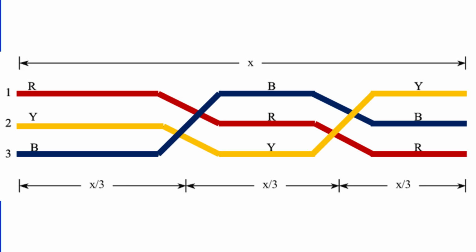Another issue is that for accurate neutralization, transposition of transmission lines is necessary. Without proper transposition, the system capacitance becomes unbalanced, which throws the resonance off and reduces the effectiveness of the coil. So while the arc suppression coil is a powerful tool, it does require careful adjustment and system design to work optimally.